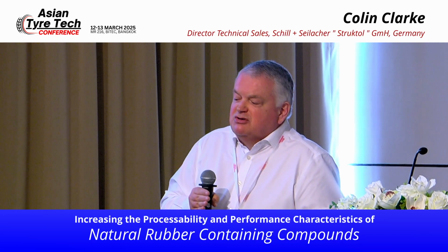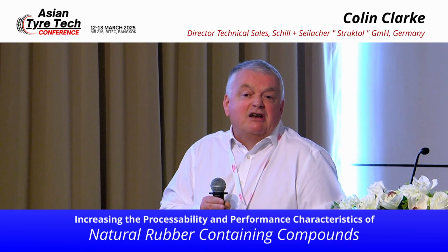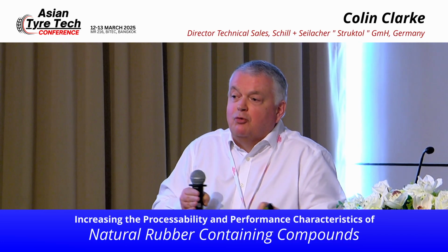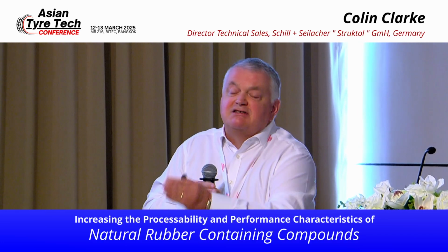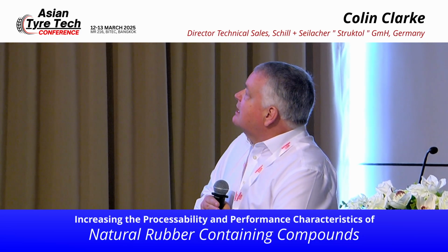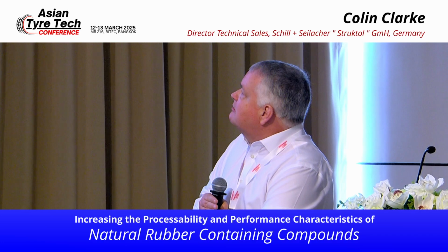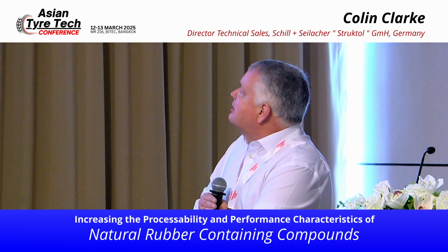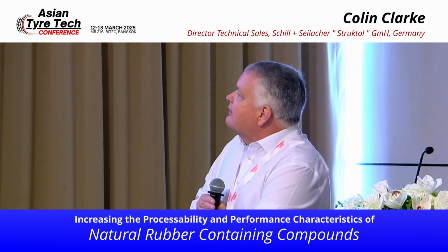Some canny, smart companies might say, actually I don't need any peptizer, let's just mix for a little bit longer. Why worry about that? We have more time, more capacity, I'll just extend the mixing because this will break the natural rubber down more. So we'll look at that: control compound, mechanical mastication, for 3.5 to 4.5 minutes. The others are 3.5 minutes each, and we'll compare those.